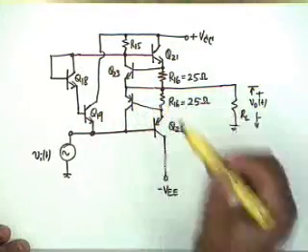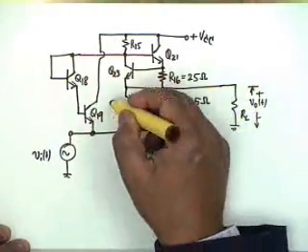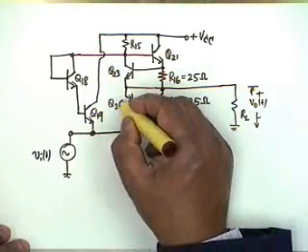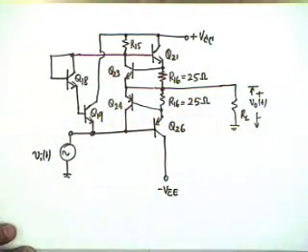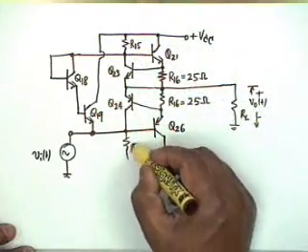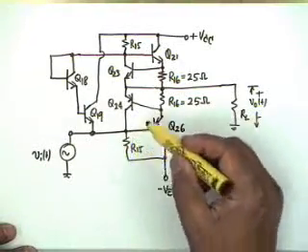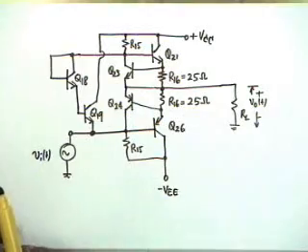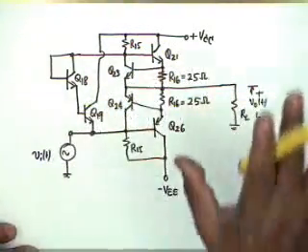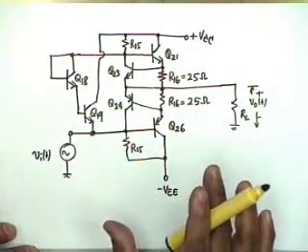absolutely symmetrical. This is Q24, is there a 24 here? No, this is Q24. Okay, and like R15 there is an R15 here. VCC and VEE are usually identical. Why is this R15? To be able to drive this transistor, the PNP transistor. Okay, this is the actual circuit, what goes on inside the 725, actual circuit of the output stage of a mu A 725 amplifier.